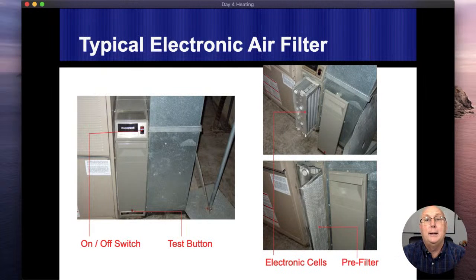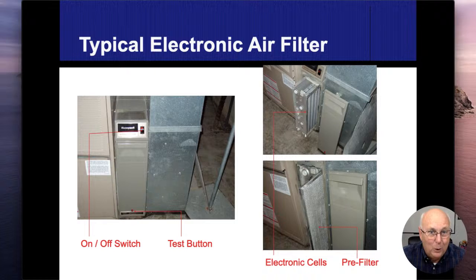So, electronic air filters, they also have certain directions. There's supposed to be pre-filters and post-filters. Those can come out and either be hosed off or put in dishwashers. I heard people get good luck with that. The other ones, it's nothing but a big bug zapper, as the dust comes in there.